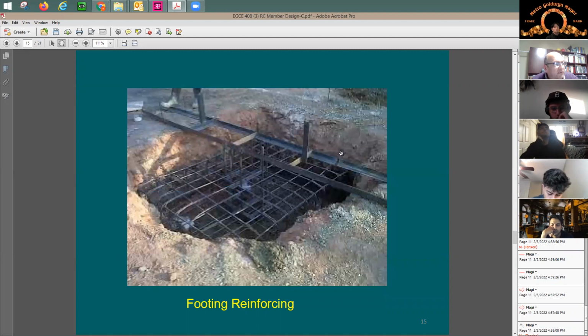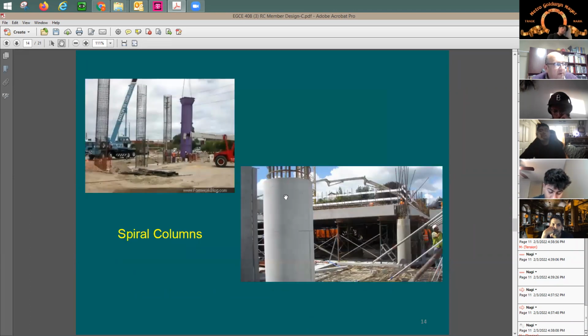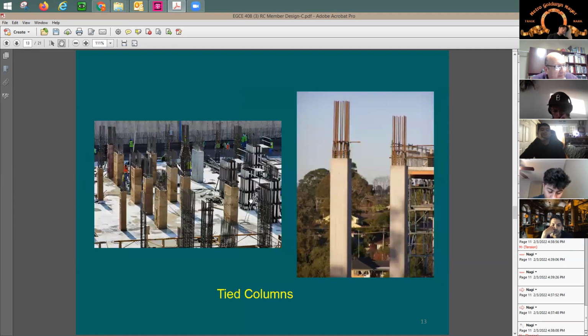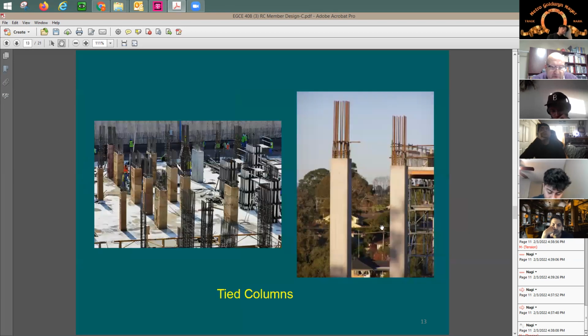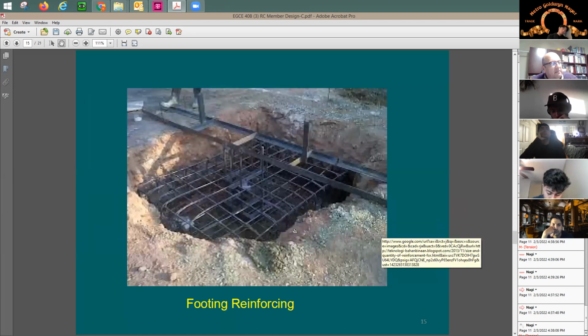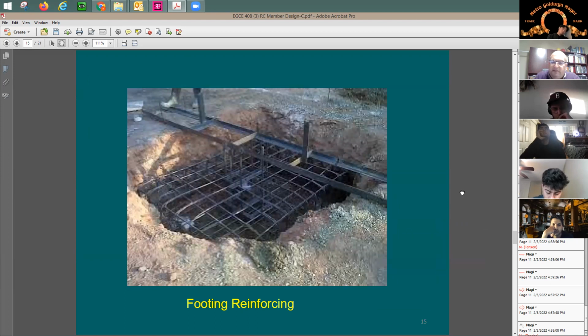If you look here at this footing, there is no formwork, right? We use the soil just to make it cheaper. We just dig a hole, and you see it's kind of irregular. It is not really straight. It is not like the formwork. It's not like this column. You see how the column is gonna become smooth and perfect. It's gonna be flat like this column here, or like this slab here is gonna come flat and perfect. And then we say, actually, to put a form here around the footing is gonna be a cost item, and you'd like to save it.